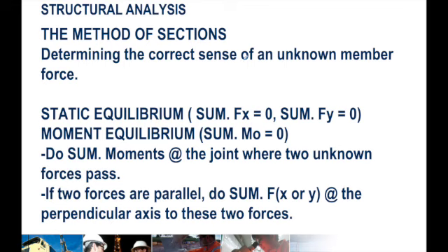So here, how to determine the correct sense of an unknown member force. We did this from our previous lesson when we were assuming the direction of the support reactions, and of course identifying how many support reactions there are for particular types of supports and connections. Again, you need to do summation forces in X and summation forces in Y must be equal to 0, as well as moment equilibrium. Summation moments should be equal to 0.